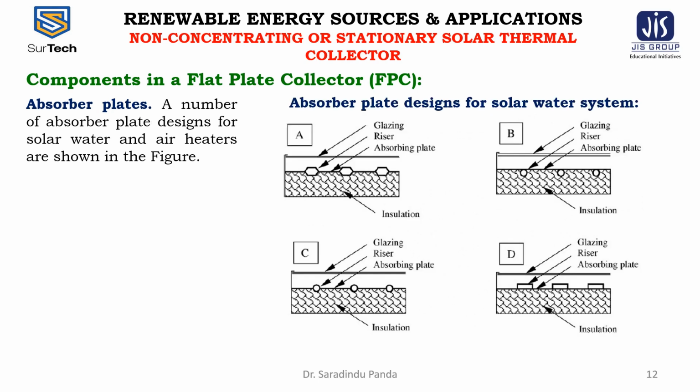The figure D shows the use of extruded rectangular tubing to obtain a larger heat transfer area between the tube and plate. The mechanical pressure, thermal cement or brazing may be used to make the assembly. Soft solder must be avoided because of the high plate temperature encountered at stagnation conditions.